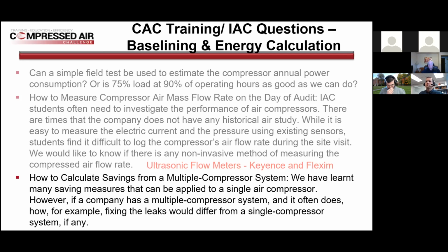The other one is a pump down method, where you calculate the volume in the system, and you take it from line pressure to 50%, and then you calculate how quick it happened and what the rate of fall is. That one you can still do with multiple compressors, because again, you're pumping up the system. You could see how many of the compressors it takes to pump up the system, and then when you do that drop down, it'll give you an idea. But since you're calculating flow, it won't have a big impact on it when you're talking about compressed air leakage.